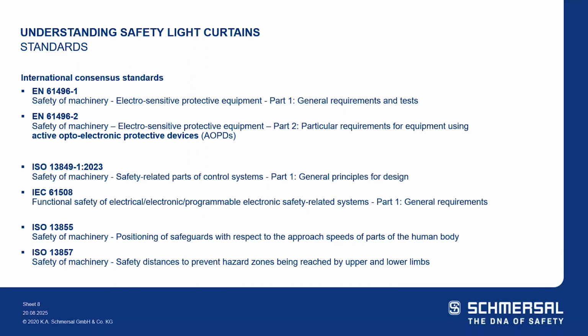Some general international consensus standards that are applicable to light curtain applications. You have EN 61496-1, which is your safety of machinery, electrosensitive protective equipment, general requirements and tests, as well as Part 2, particular requirements for equipment using active optoelectronic protective devices, AOPDs.